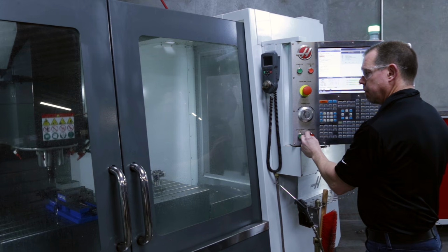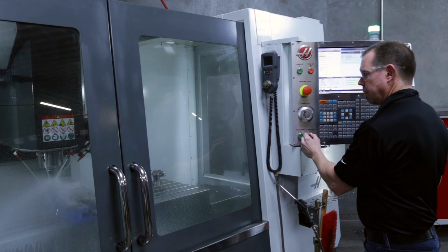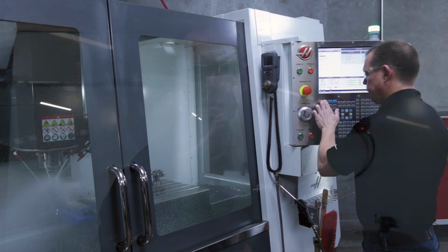But looking isn't all we're doing here. We also need to listen. Different materials make different sounds when they are cutting, and in general, they all make a nice uniform low tone. A cutting operation that is squealing and making a chattering noise is not cutting properly. So let's listen to a couple of examples.